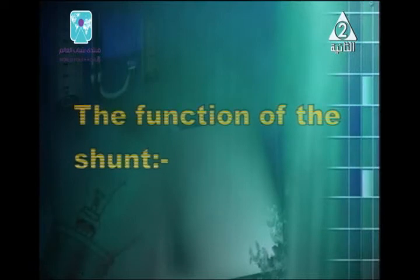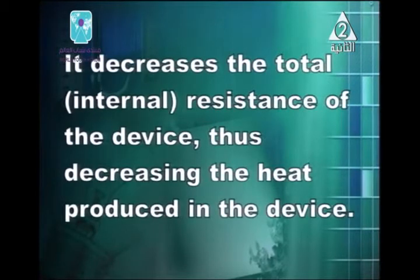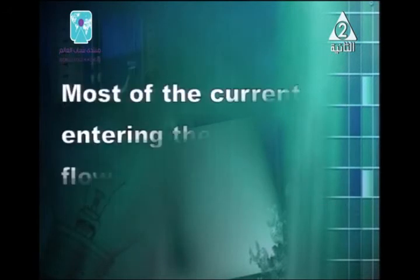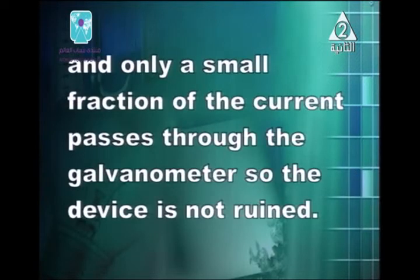It extends the range of the device. The shunt increases the range of the device. It decreases the total resistance, the internal resistance of the device, thus decreasing the heat produced in the device. And as a matter of fact, most of the current entering the device flows through the shunt, and only a small fraction of the current passes through the galvanometer, so the device is not ruined.